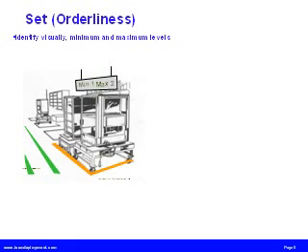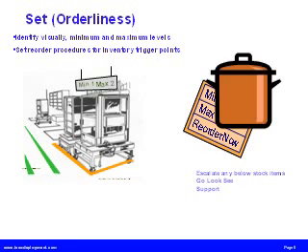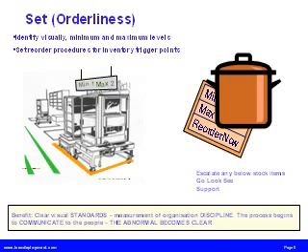It's no good setting a low level for, say, widgets at 100 if you use 50 a day and it takes 3 days to get parts ordered, because you will obviously run out. If items are below minimum levels, make yourself sure that the parts have been ordered. Go look and see it's done. The benefit is again setting a standard that communicates with the team instantly. Anything unusual is immediately seen.